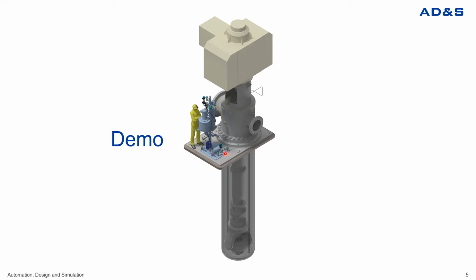And one of its functions is to provide a flat and level surface onto which the machine sits. It also transfers the loads of the equipment onto the foundation or the ground. Failing to do so will result in either premature or catastrophic failure of the system.